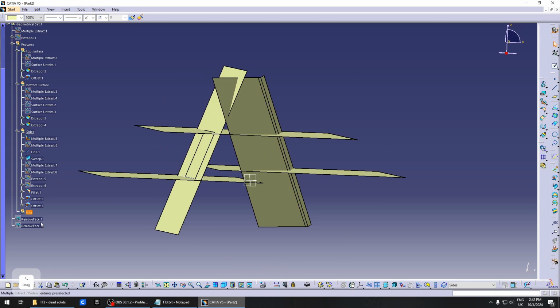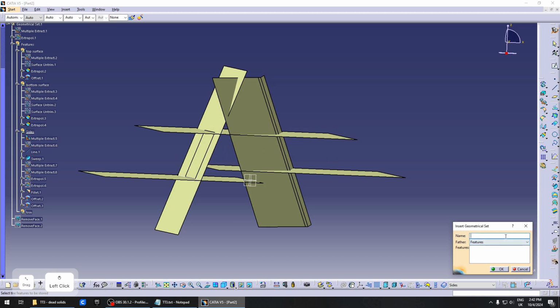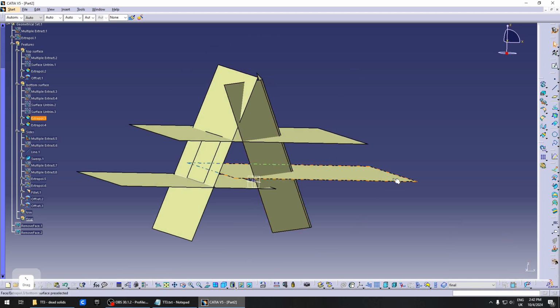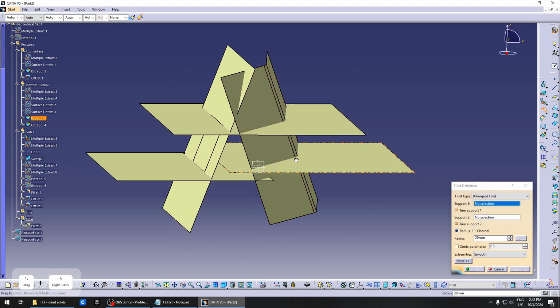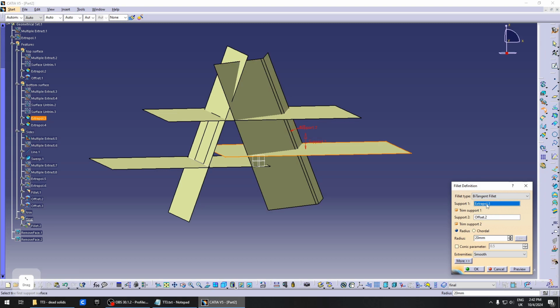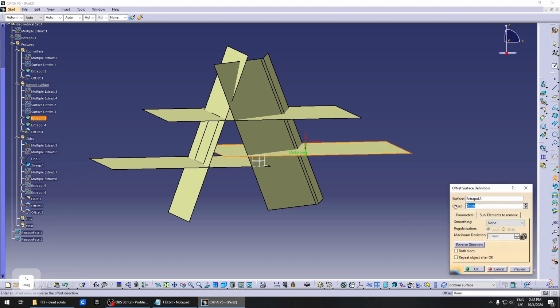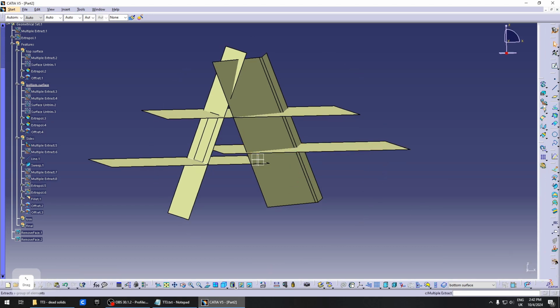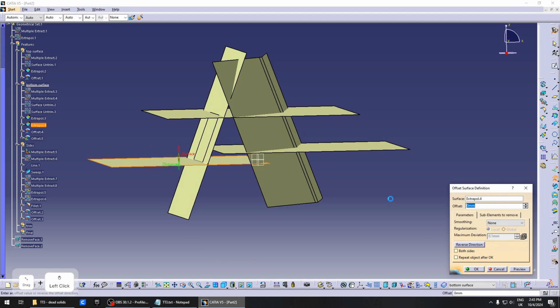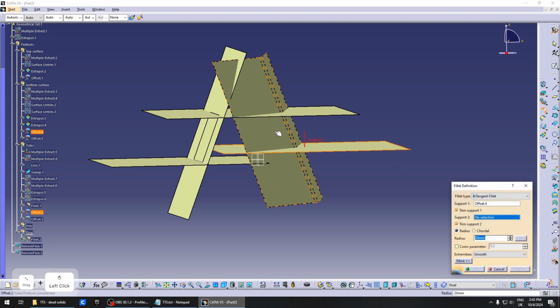And we then go ahead and create a different geometrical set, which you call final or whatever, and you start doing these assemblies for the features. So we have the extrapolate. Sorry, here we just extrapolated the surface, but we could also put an offset as a control. Good. And then we go to the final, and then we use the shape fillet on the offset.